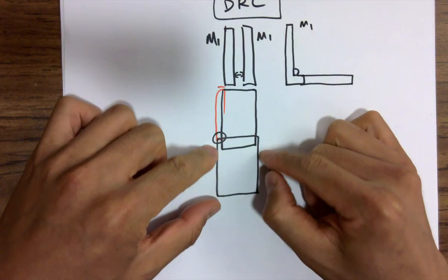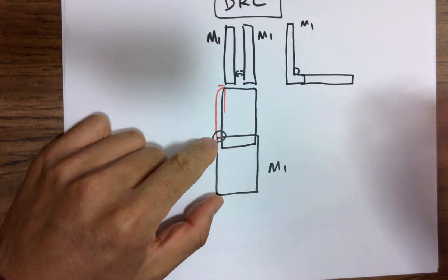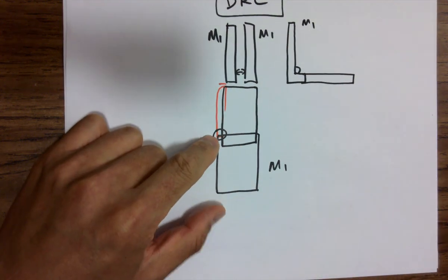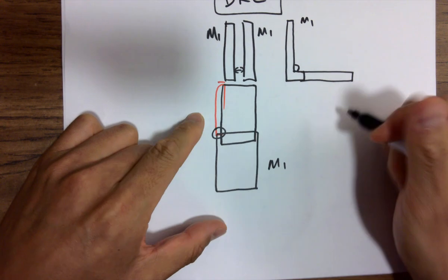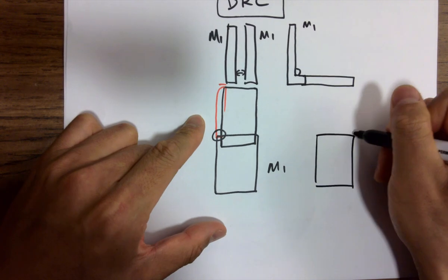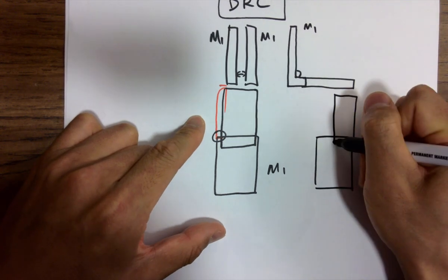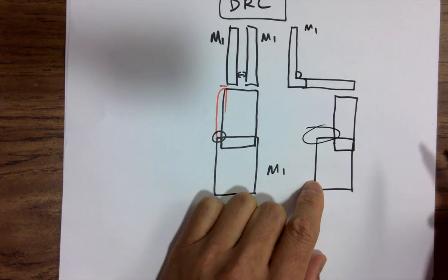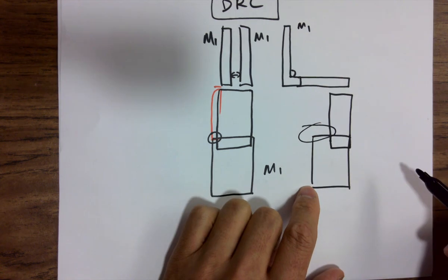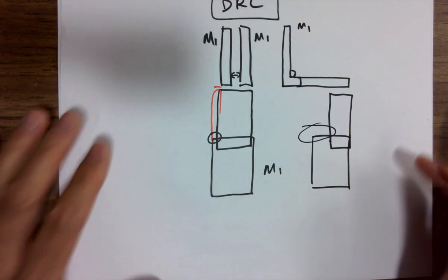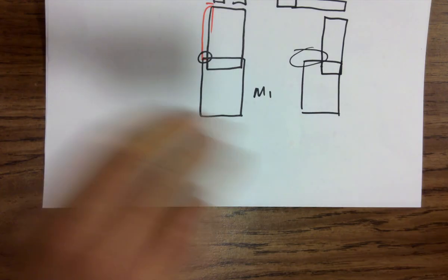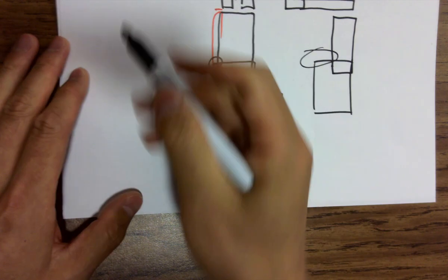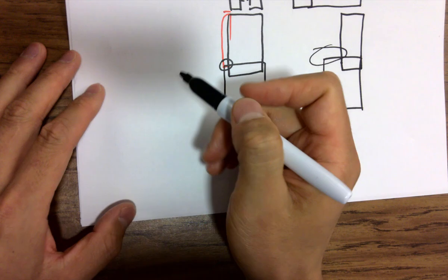Whenever you are laying out traces, make sure they match. If they don't match, maybe try to push this one a little bit to the side, so at least one side matches. You can give an overlap so it's making a connection, and you are giving a bigger corner here, so it's able to resolve it. It's another problem you need to know. So the design rules are not just for metals, but for all different kinds of corners.